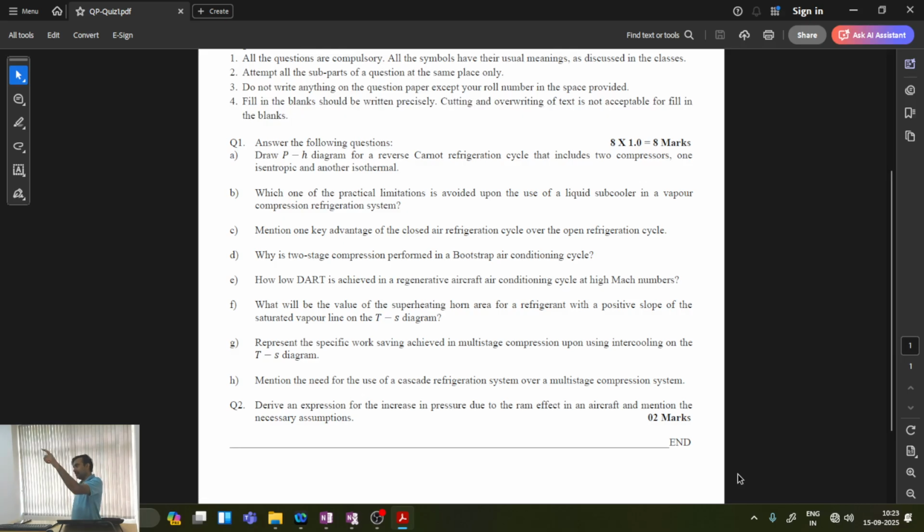For example, I am using some high pressure working fluid. I have explained two types of working fluids. High pressure working fluid means its boiling point is towards the higher pressures. So in that case what will happen? Whenever we operate it at very low temperature conditions, corresponding to that its pressure has to be maintained less than the ambient pressure.